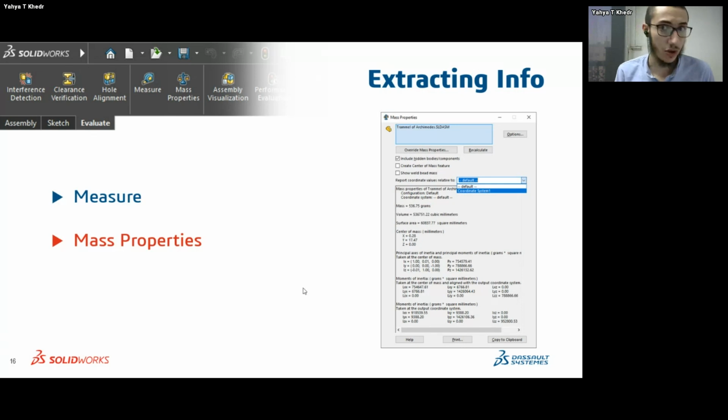And when it comes to the center of mass, it's not only about the materials and volumes and density, but it's also about the reference. Because when I say that the center of mass is x equals 5, y equals 2, and z equals -20, according to what? 5 centimeters from where? -20 in which relation? Is it to the origin? Is it to another reference?